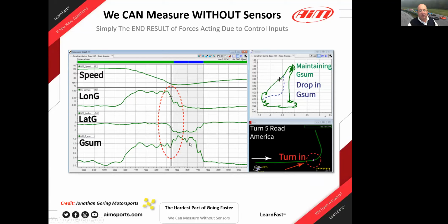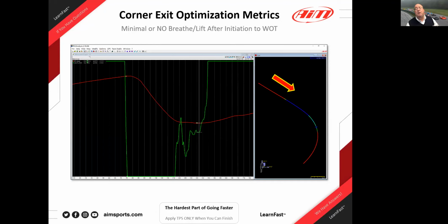Really, really good. Super. Yeah, you could add a slope channel if you like, but all you've got to do is walk the track and you can figure that out. It's not evident in the car. That's the key thing. For those people who never walk the track and just focus on driving it, you do need the slope. If you walk it, it's better too. And camber, there is a camber gain, as you not only gain camber, but also lose it. And that's why nothing is static. It's all dynamic. It moves all the time. Camber of the track, not camber of the front suspension.